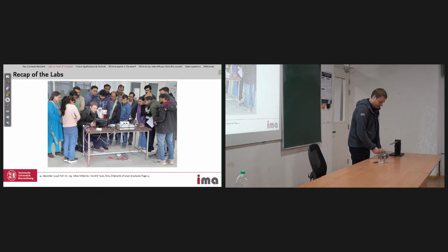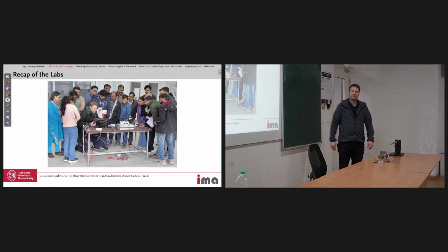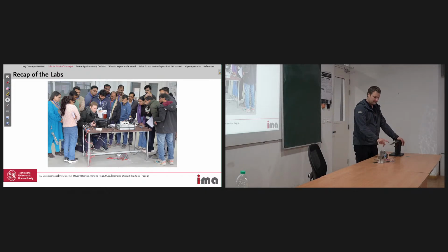Okay, this was our third experiment, and today was the first day where we used some dynamic testing, and we first of all determined the eigenfrequencies, the first two eigenfrequencies of this beam. By the way, you can calculate them as well. But today we determined them experimentally, and we took the measurement of the displacement here and determined the frequencies. And after that, we did not, but we tried to get the mode shapes by determining the displacement at several points along the length. Okay?